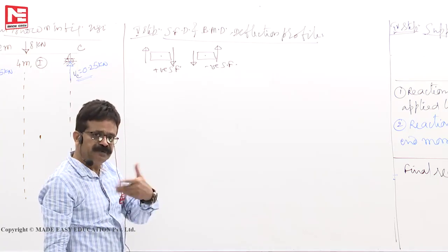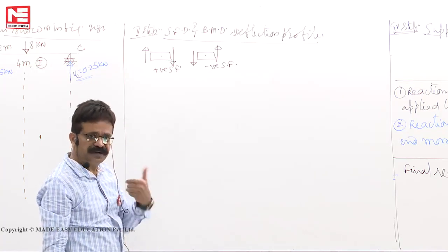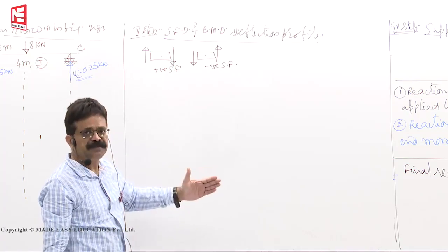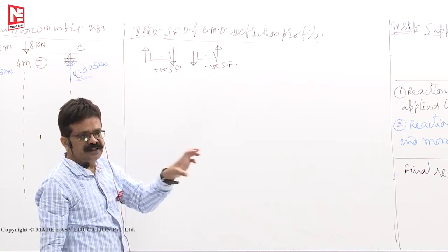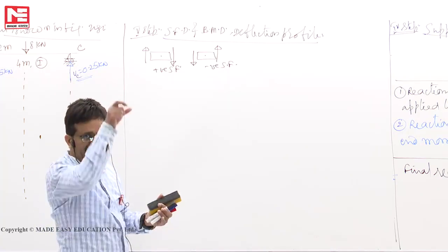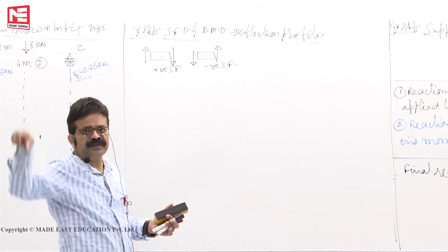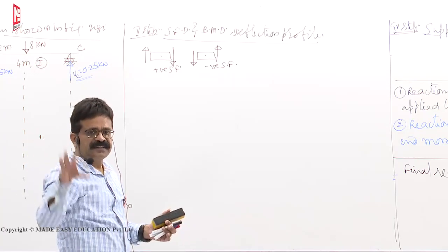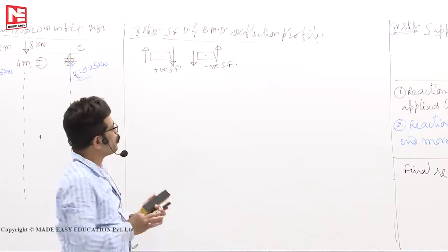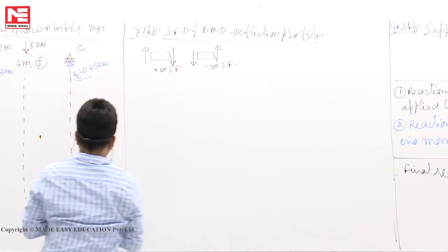That magnitude will be more, and the effect also will be more, if you have a deep beam or the web is not solid. If the two flanges are connected only at intermediate locations, with gaps in between, in such cases shear deflection also we will consider. Now this is a positive shear force.